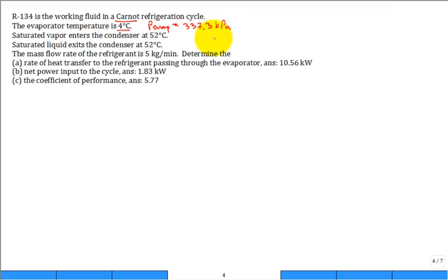Somebody has an ice pick. They come up to that evaporator coil. They poke a hole in it when it's running and the pressure is 337.3 kilopascal. Does air rush in or does refrigerant rush out? It rushes out because atmospheric pressure is around 100 kilopascal.